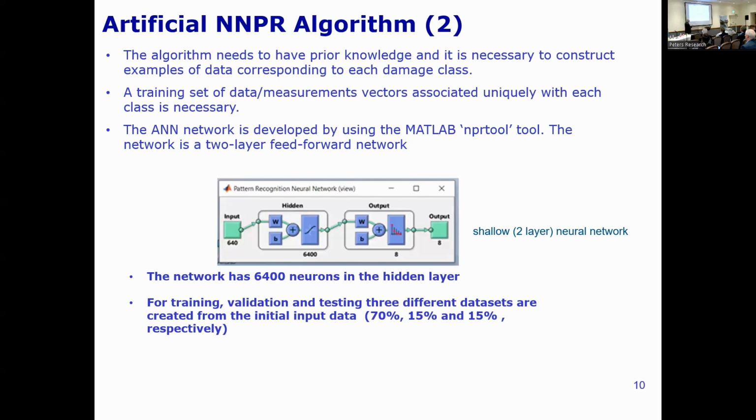So, okay, when we have this, luckily, we don't need to do everything from scratch because there are neural networks already in libraries, and we use MATLAB libraries. There's a tool called Neural Pattern Recognition Tool, NPR tool, and that works very well. You can code it, and we get some results. So that's an example. For training, we have an input. We input the data set, it goes through those, and goes to output. And when it is trained, we get the network, with all the neurons now trained, and, remember, the bias coefficients and weight coefficients now adjusted. So it's all about mathematics here.